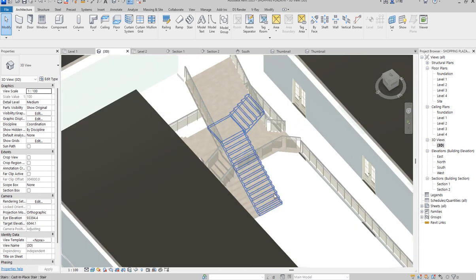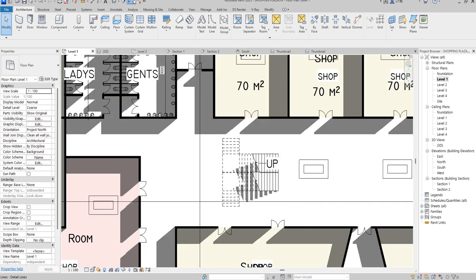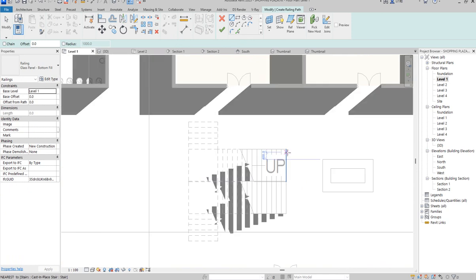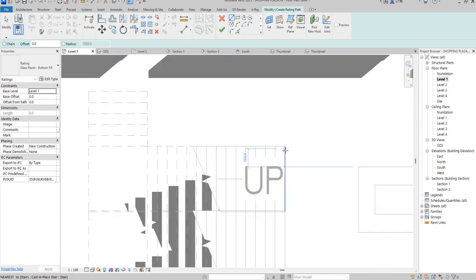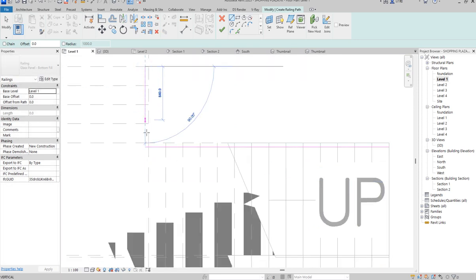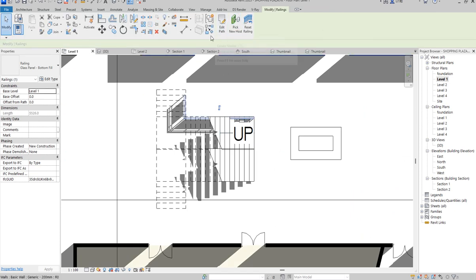So in the ground floor railings, you do the same method and we achieve that. Let us quickly go there and do the same thing we've done before we proceed to start working on the elevation. The railings, you click and say railings. Remember, we start from here and we are going up. You click finish, then you say host, pick host, and it will pick the host here.